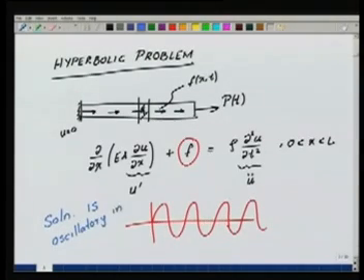And we had discussed that as far as resolution of the solution in space was concerned, in order to get the natural frequencies and the modes properly, our finite element approximation in space had to be sufficiently fine to be able to represent the mode properly. Similarly, in time, when we do the temporal approximation, our approximation in time should be sufficiently fine to be able to capture the corresponding oscillatory behavior in time. This is something we have to keep in mind when we go ahead and construct temporal approximations.